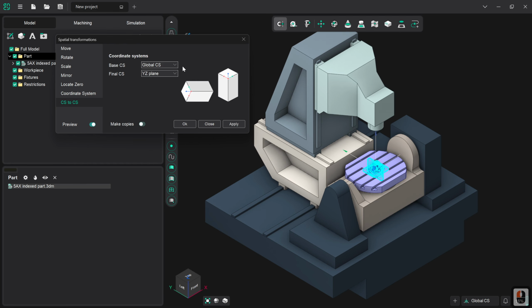You can also map external coordinate systems onto the part coordinate system as well, should you so wish. This is just a slightly more complicated version of what we had before, predicated more on planes and any other predefined coordinate system that you already have. It's the kind of thing that's very, very useful if you're importing multiple elements into a particular piece and you want overall uniformity of orientation and placement.